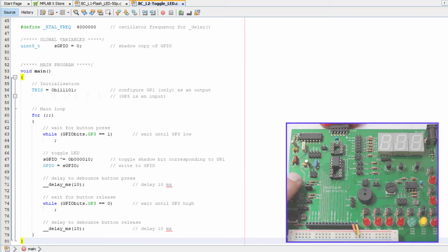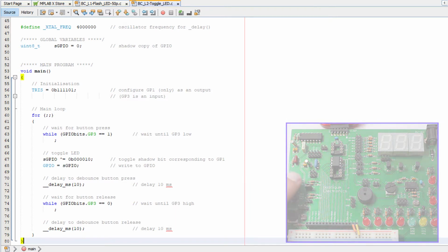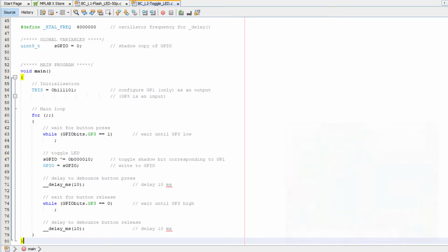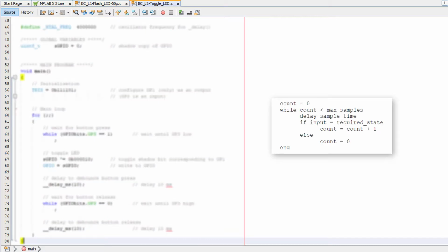There's still a potential problem though. Sometimes we get short spikes or glitches in input signals, maybe from some sort of electrical interference, but if you only have a simple debounce delay, there's no way to tell the difference between a glitch and the start of a switch closure. A common way to filter out spikes, as well as bounces, is to check that the switch stays consistently open or closed.